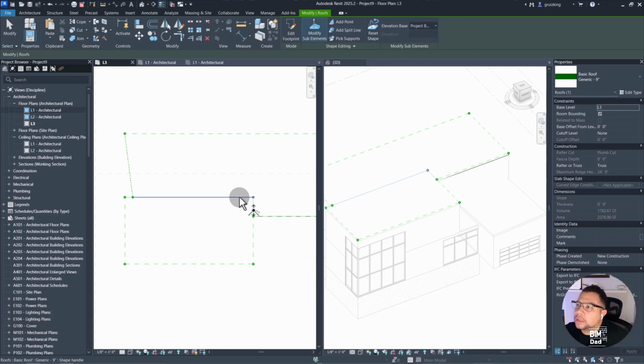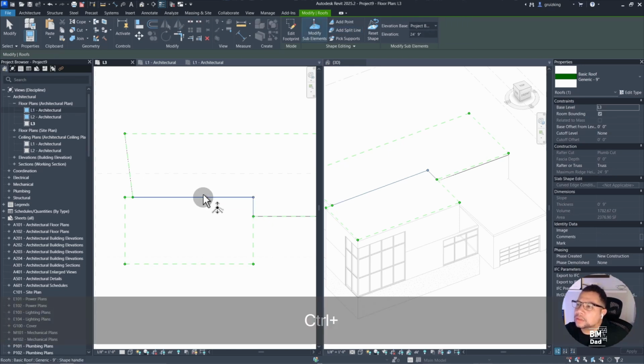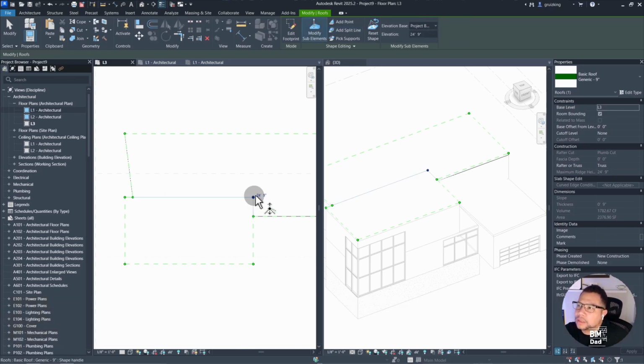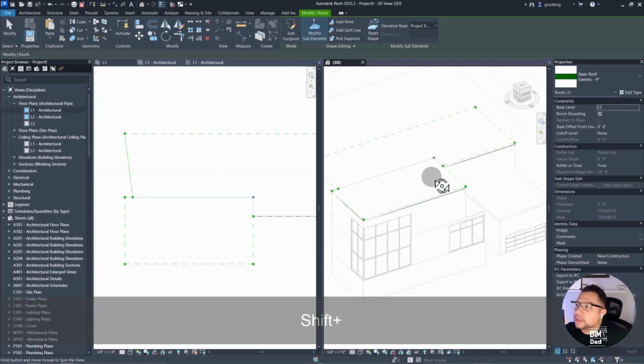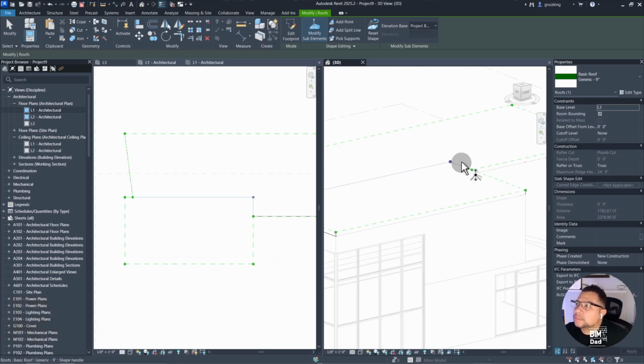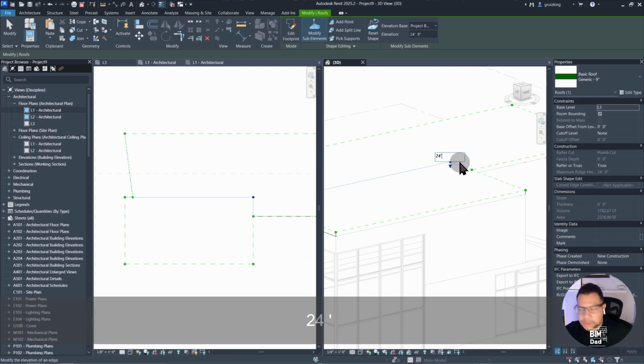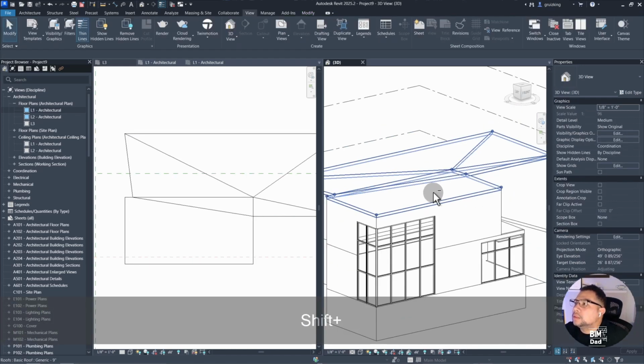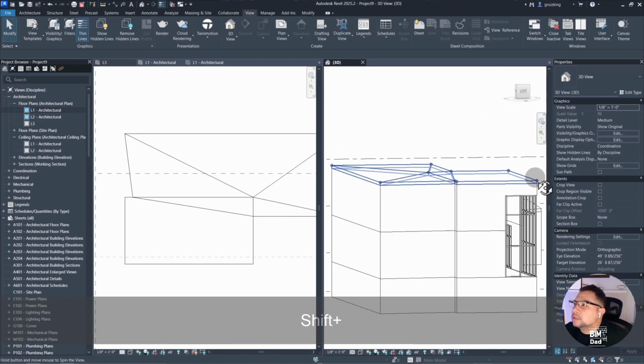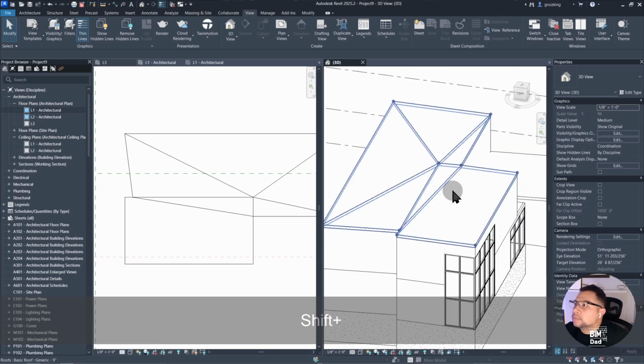So if I wanted that set of lines to go down, or even just that one point, we can do that. All right, so I can select that. Right now I'm at 24.9. Let's go maybe 24.6. You can see that now we've created a sort of drain point.